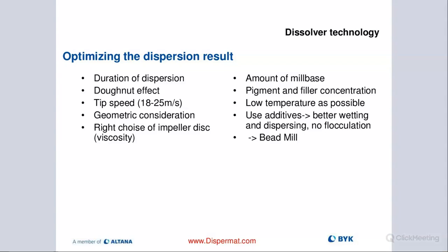When we're milling, it's absolutely critical because that's when we really put in even a lot more energy, and then it's an absolute must. Pre-dispersing, some people think they can get away without using double wall containers because they're only pre-dispersing sometimes only 10 minutes. It's okay. But if you pre-disperse for longer periods, like you go out to 30 minutes, I think it's highly recommended that you're definitely cooling your mill base, especially when you're running solvent-based products. Then it could become a safety issue.